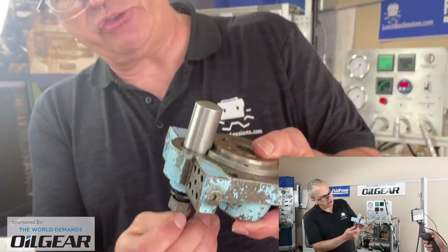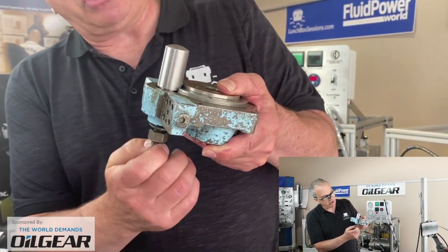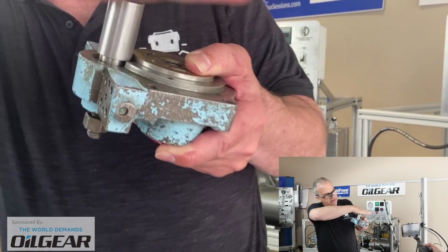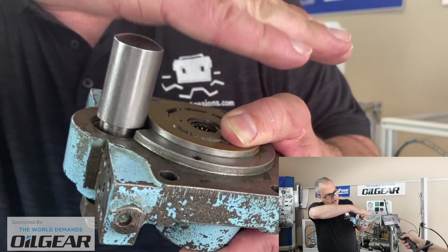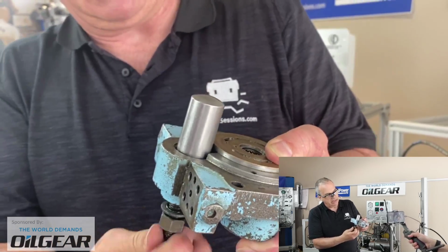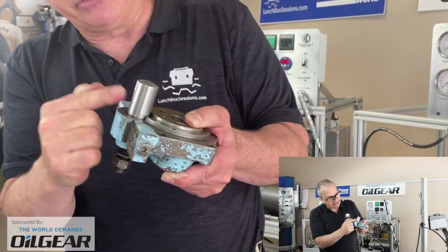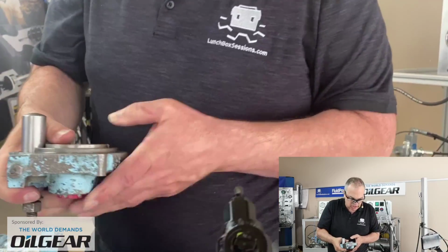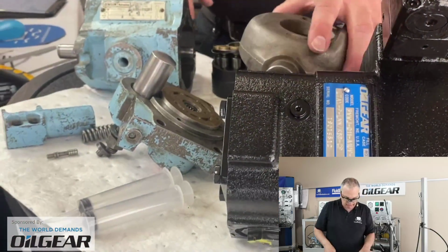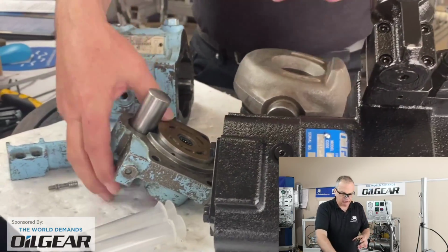If I was adjusting the maximum volume stop, I think you can see that the control piston is extending, so we'll no longer get the 20-degree angle. Perhaps we're only going to get the 10-degree angle unless we turn it back out and allow the pump to be larger. So this literally limits the maximum size, the maximum pumping displacement volume of the piston pump, right? And so what are we supposed to picture?